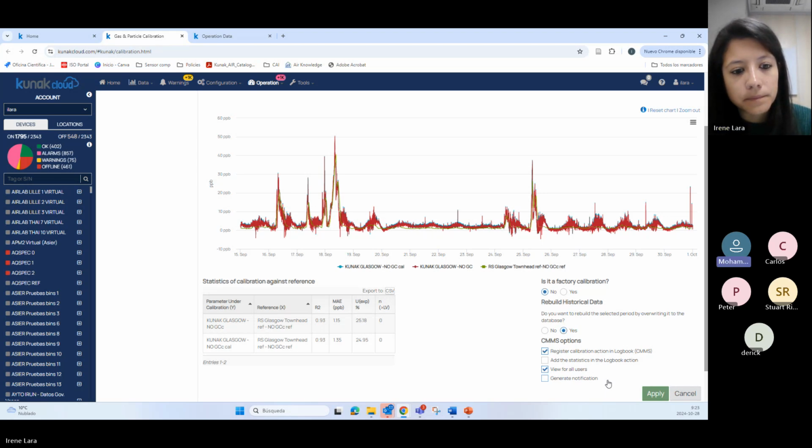But for span calibration, we don't need that every season. No, because span, or sensitivity, is how much the sensor signal responds to the target gas, and this is not dependent on the average temperature. So it is not needed to adjust it every season. Okay.